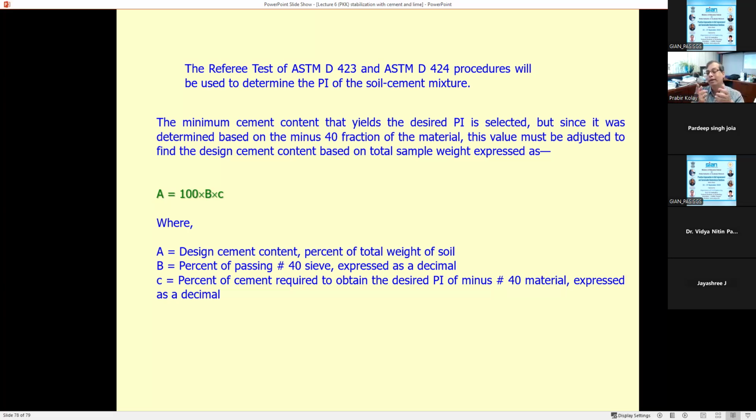Okay, so it depends. And then for the durability aspect of GGBS, I'll show you some results with different mixtures. The durability aspect is basically this: you prepare a sample and then do accelerated freezing-thawing or wetting-drying and see what is happening.